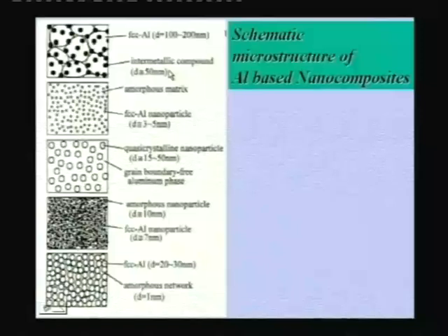All these kinds of alloys can be melted, and in the liquid state we all know that all of them are soluble. So if you have high solubility in the liquid state, dissolve all these elements in the liquid state and then cool it rapidly, so that you ultimately get a supersaturated solid solution, with higher solute atoms dissolved in aluminum. Now start doing age hardening so that you can have precipitates, and that's how you can get this kind of intermetallics and produce intermetallics like that.